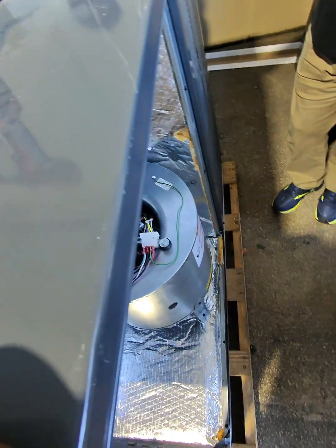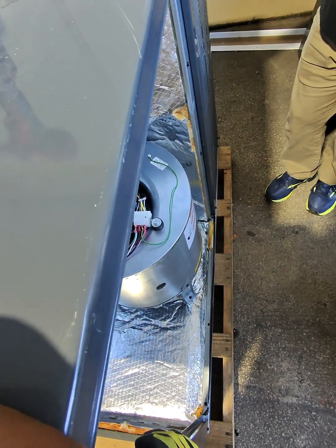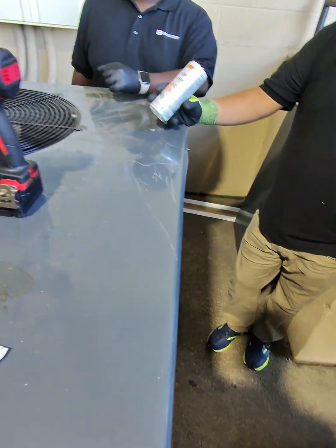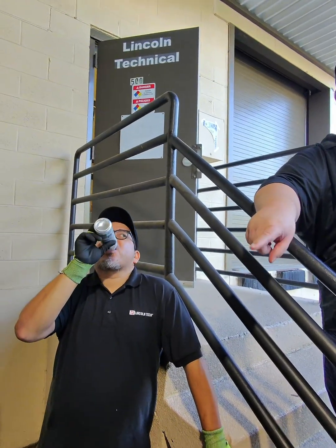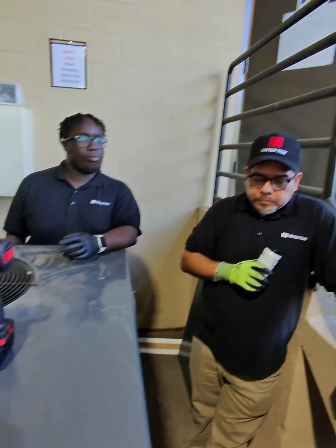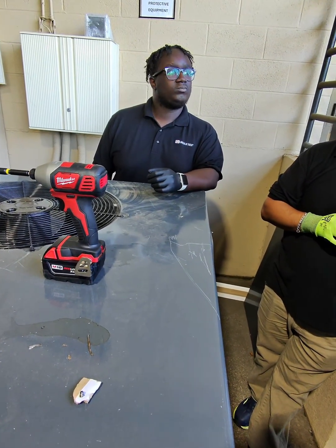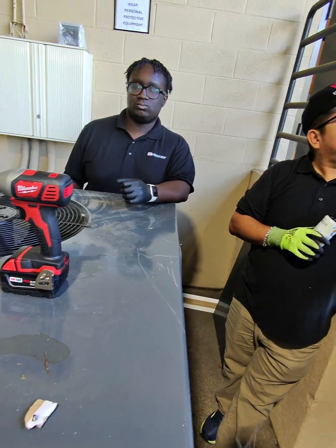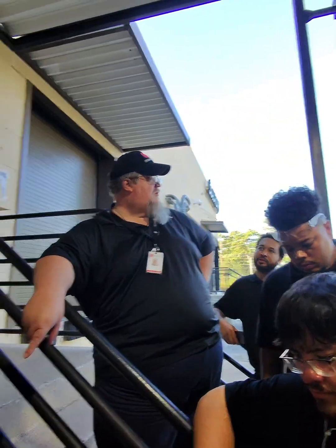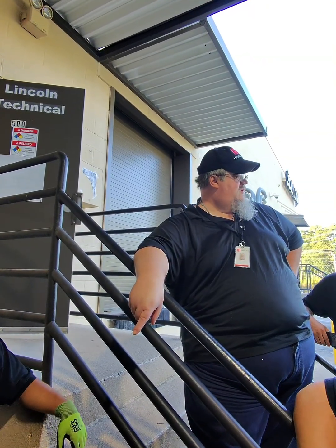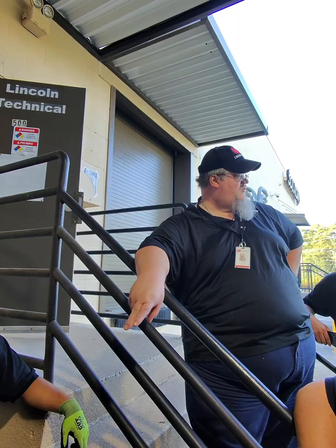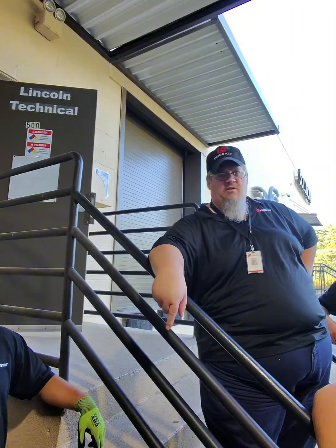When you see an ECM motor like that, what do you automatically know about that motor? Remember I told you, as service techs you got to remember. You have 208, 230 single phase coming to the unit. So what is that motor? It's single phase and three phase, there's no two phase. So it's a three-phase motor.